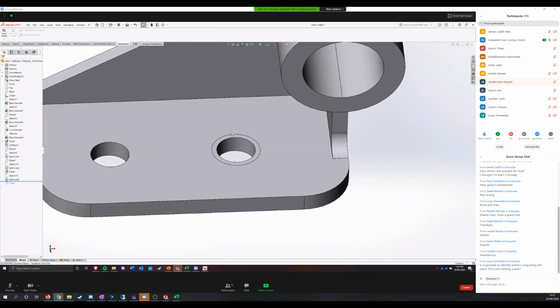So if you understand the way that the nodes are behaving next to your fixtures or next to your forces, then you can really start to identify singularities just by looking at it. But again, you can't properly tell that it's a singularity without doing your convergence study.